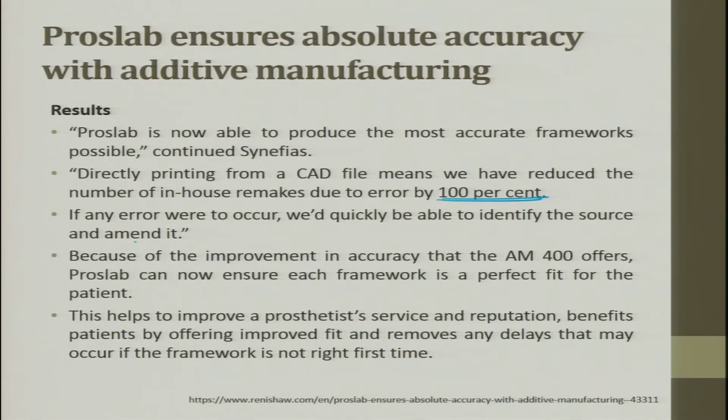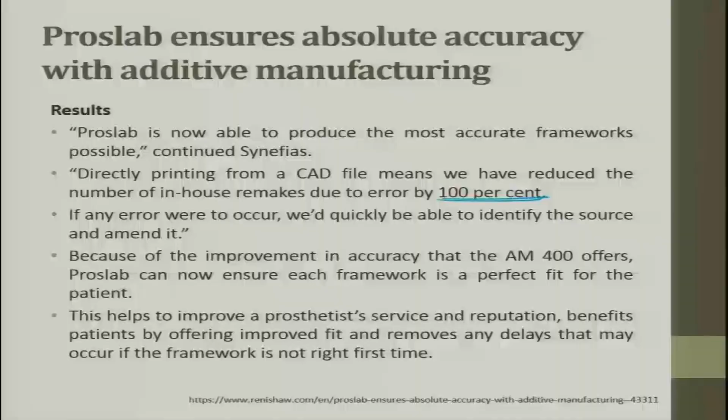Nowadays you have very good simulation software. These simulation softwares show layer by layer how it is building, when the laser moves how it is building, is there any porosity coming, is there any delamination happening between layers, whether the melt powder is perfect. So, you should have a uniform homogeneous heating.